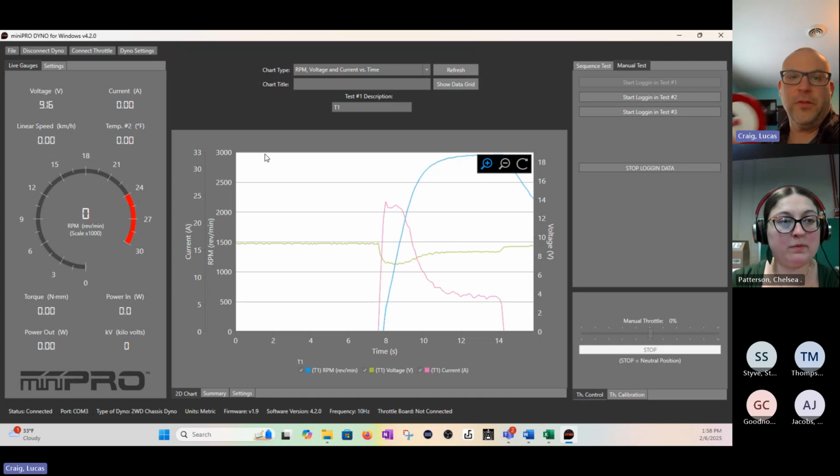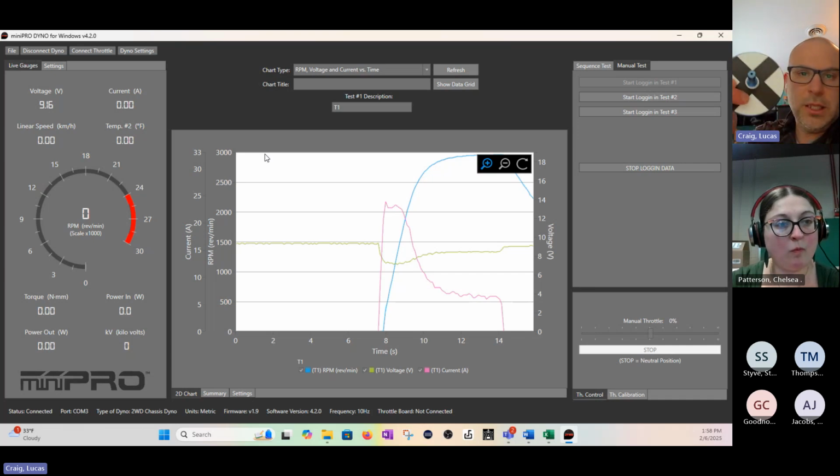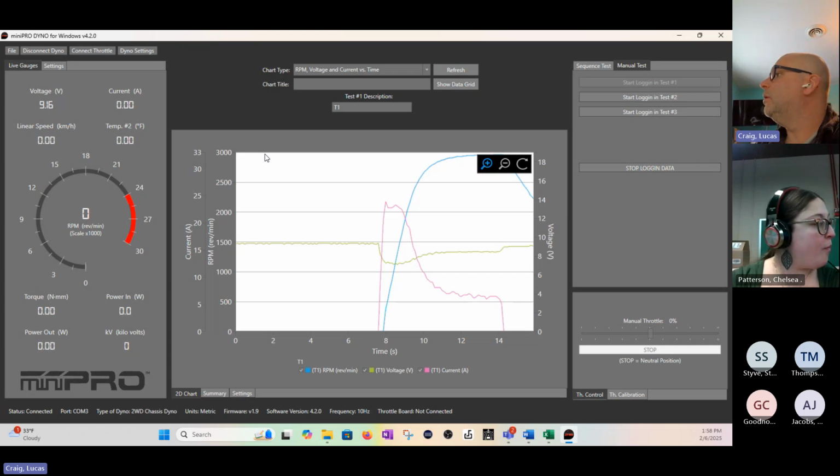Now, the flywheel that I had in the housing is actually 124 millimeters. I think it's 10 millimeters thick, just like this one, but it's stainless steel. So it's a lot heavier. It has a higher mass moment of inertia. And I put it on here because these RC cars need a higher mass moment of inertia. If I put this one in, this thing would just crank up and there would be hardly any load on that RC car.